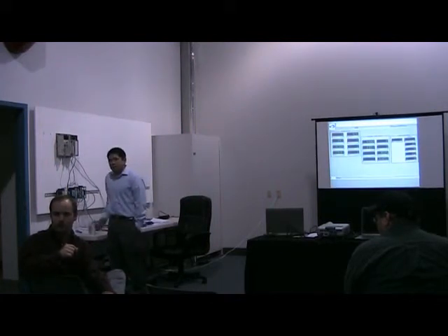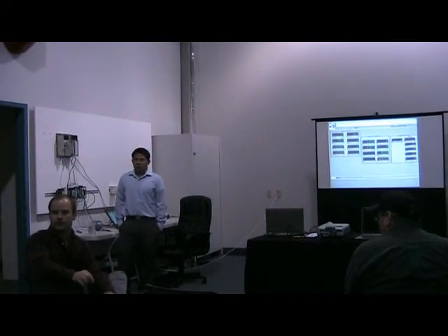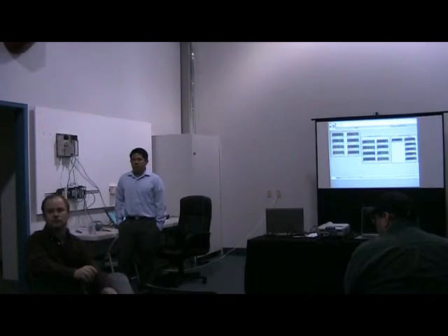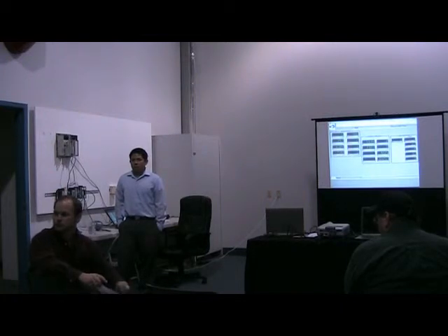Yeah, they do a fingerprint of them when they manufacture them, and it checks the electronics within both the sensor and the transmitter. It measures a bunch of values, like impedance of the coil and all that, when it's brand new. And then every number of years you can check. It'll do internal measurements on itself and tell you how closely that compares to what it was when it was brand new. Yeah, ABB does that. They built that onto that card.